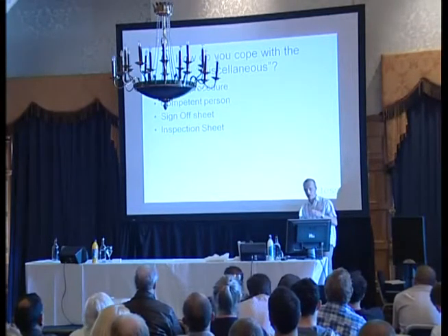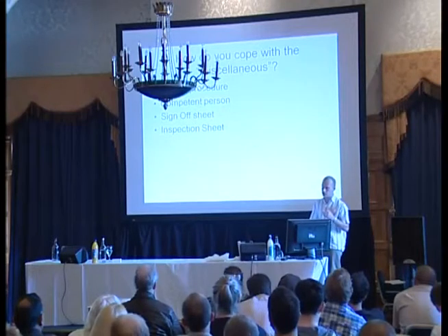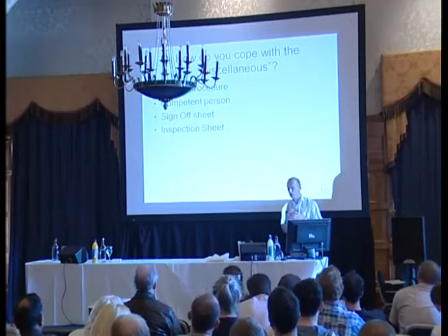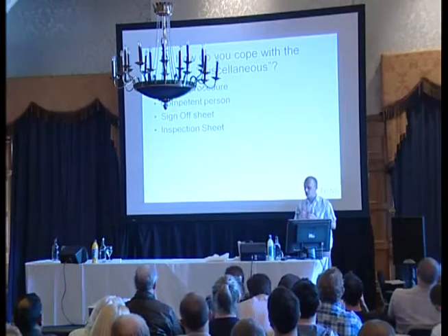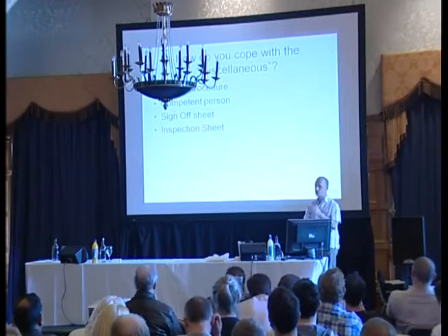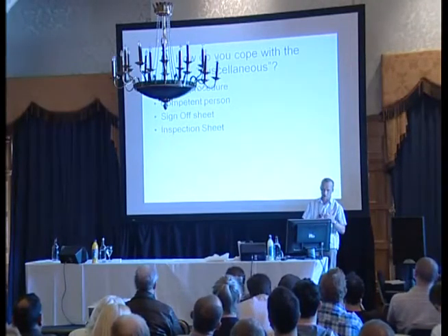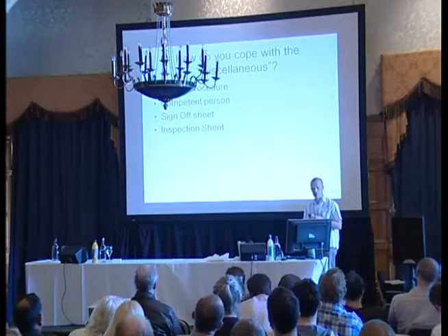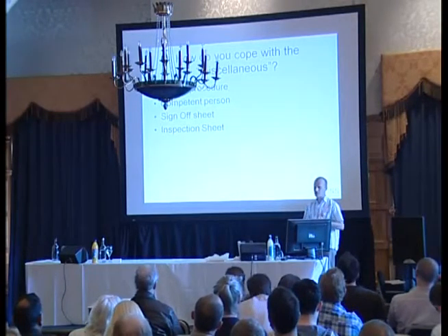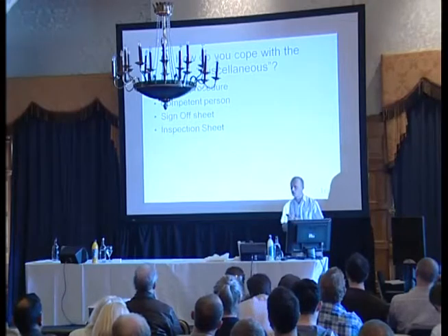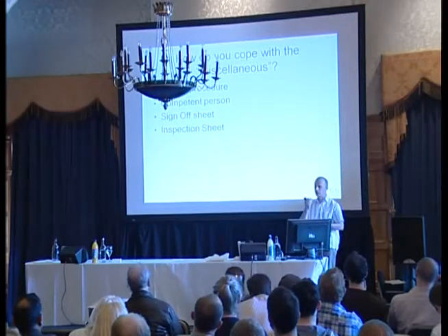Another thing that I've thrown in here from paperwork is inspection sheets, to make sure that you know how something is behaving, to make sure you've got the critical parts of a structure that you can go through and tick off to make sure that they've been done. Is the ballast there? Are the stakes there? Are all the nuts and bolts in there?